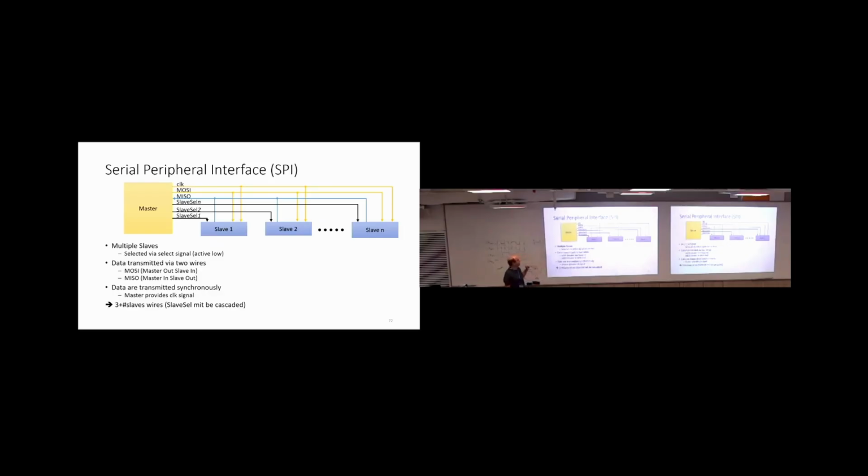But if you go for embedded systems, then frequently you have an SPI for the actual communication, or even quad SPI, so that you have more data at the same time. So if speed counts, I think SPI is better than UART. For the sake of simplicity, UART is maybe simpler. I would say so, yes.